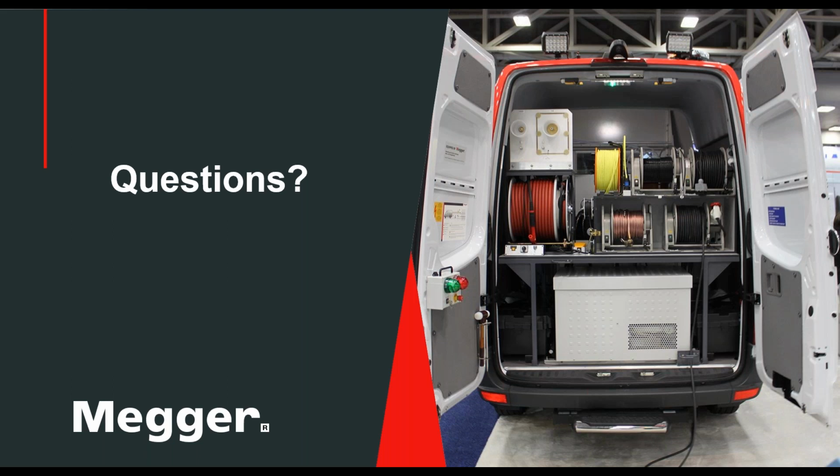All right, thanks. Also for Marshall, is the low voltage pulse radar sent out at the same time as the high voltage signal to detect the fault? Or is there a small delay to allow for the high voltage to reach the fault first? This is actually a pretty in-depth question, and we didn't talk about this at all in the webinar. The short answer is yes, there is a small delay called trigger delay.